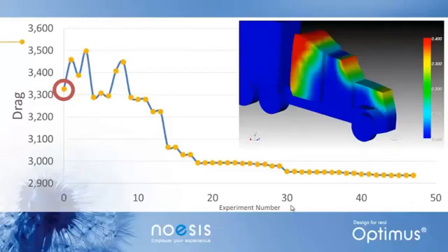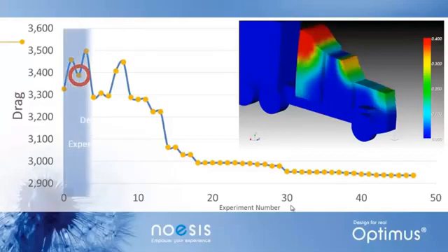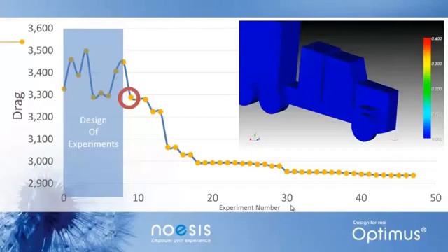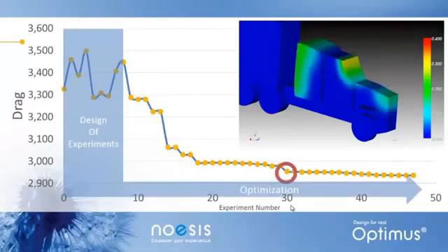With the optimization algorithm, the first thing that it does is it actually performs a design of experiments. So like you, the optimization algorithm needs to understand the relationships between the inputs and the outputs, and cover that design space. So there are a lot of hidden mathematical relationships that can't be understood necessarily by a human, which are mathematically determined. And then it automatically proceeds to the optimization algorithm, having been armed with the knowledge from the DOE, and very efficiently progresses down to the best designs.